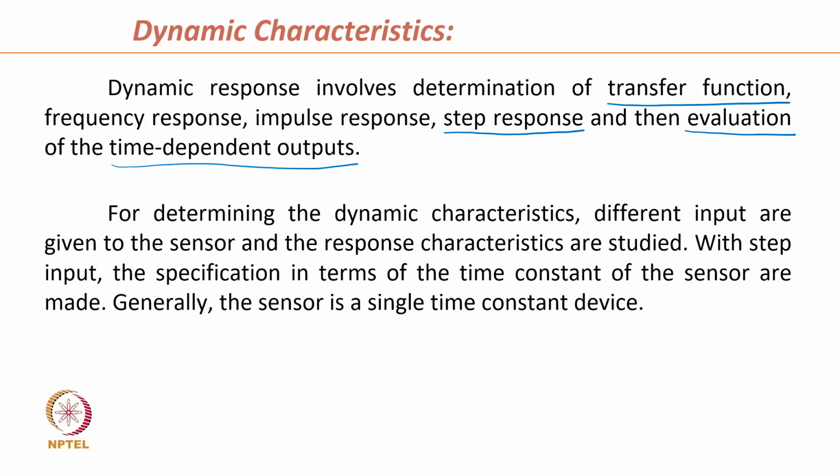So, these are the dynamic characteristics. For determining these dynamic characteristics, different inputs are given to the sensor and the response characteristics are studied, how the sensor is responding to these inputs. With step input, the specification in terms of the time constant of the sensor is generally made, and generally the sensor is a single time constant device. It has a particular time constant and accordingly it produces the output.